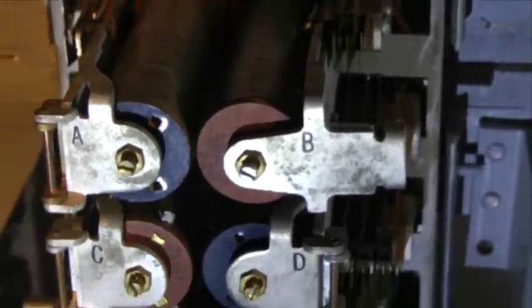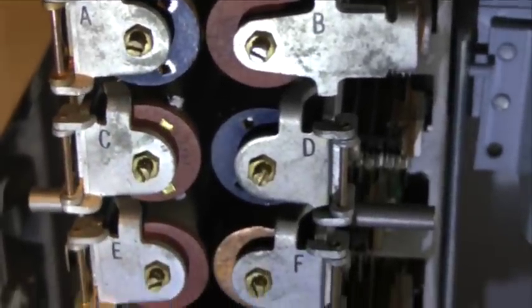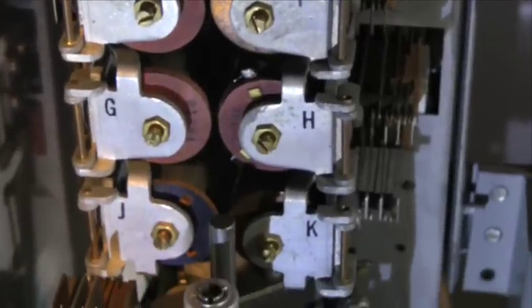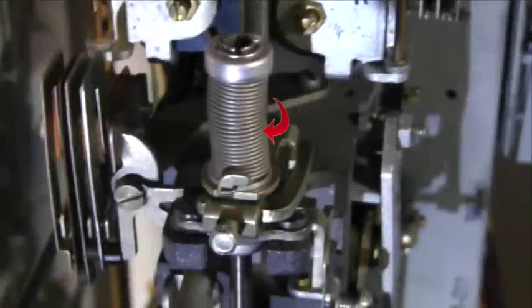So starting at the top of the connector and working our way down are the 10 relays, A, B, C, D, E, F, G, H, J, and K. We'll be discussing all of these relays in some detail except the J and the H relays, which are only used on toll calls and will not be covered in this video. The shaft spring provides the tension needed to make the shaft rotate anti-clockwise upon the disconnection of the call. The shaft spring bracket is the support base for the shaft spring.